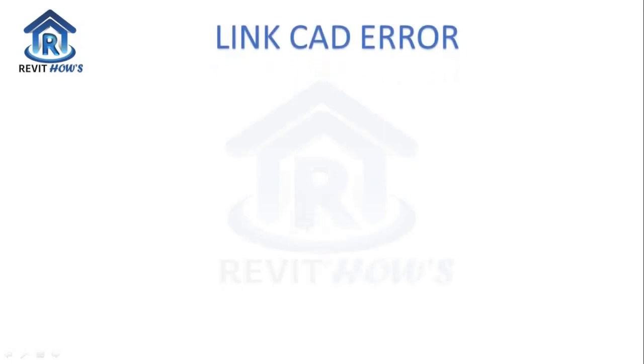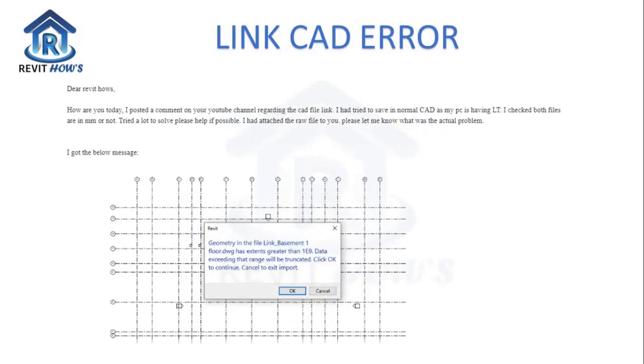In this video, we're going to discuss the link error that was sent to us. He has a problem inserting his AutoCAD file in his Revit. So he has this error: the geometry in the file link basement 1 floor.DWG has extents greater than 1E9. Data exceeding that range will be truncated. Click OK to continue, cancel to exit import.